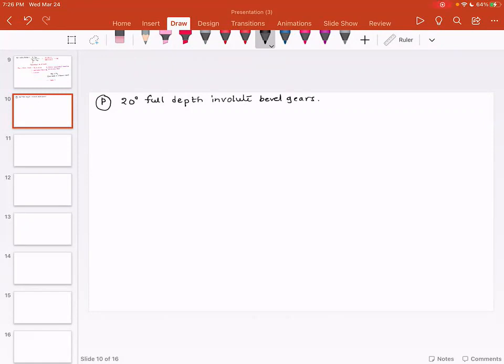And they are at the shafts at right angles. The velocity ratio is equal to 1:3. What it means is one revolution of bevel gear causes 3 revolutions of bevel pinion.